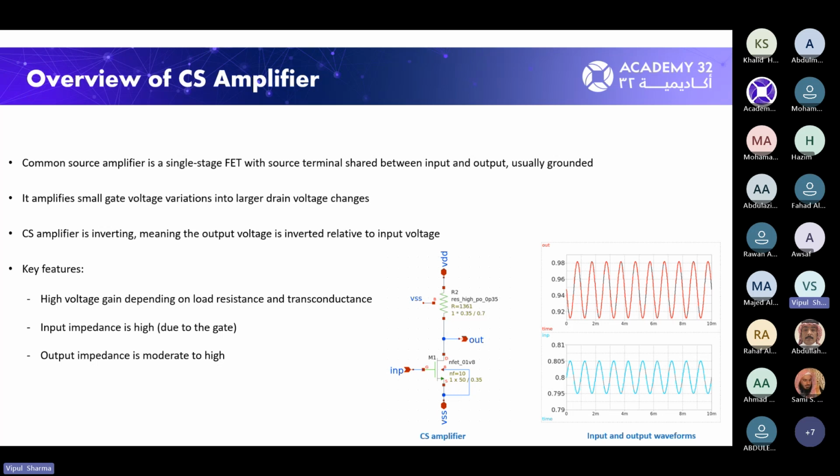So whenever you are designing some kind of cascading stage, all these criteria need to be taken care of, so that whatever output you are driving from this amplifier stage to another stage, there should be proper loading so that the signal does not attenuate while going from one stage to another. But it cannot be thought about independently. You have to take a complete cascade chain, analyze it by putting a common source amplifier in between, and try to tune your signal chain: how much gain is required, what will be your frequency response. All those things are part of the design activity.